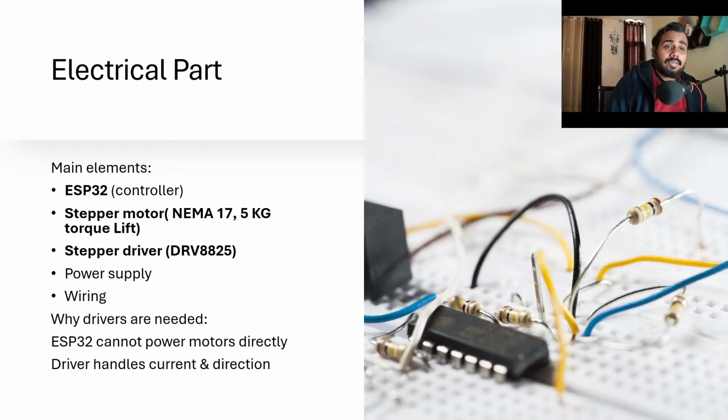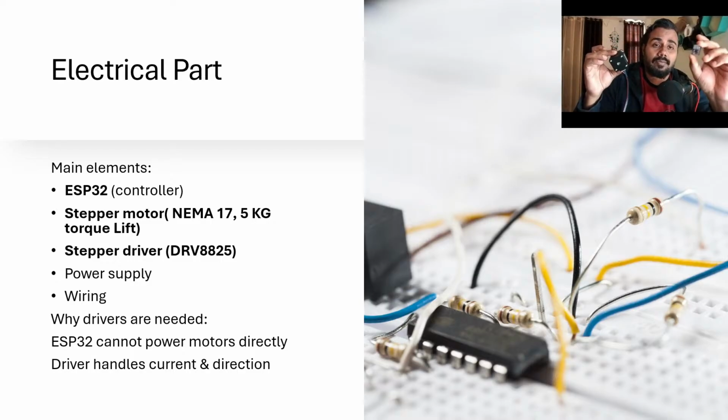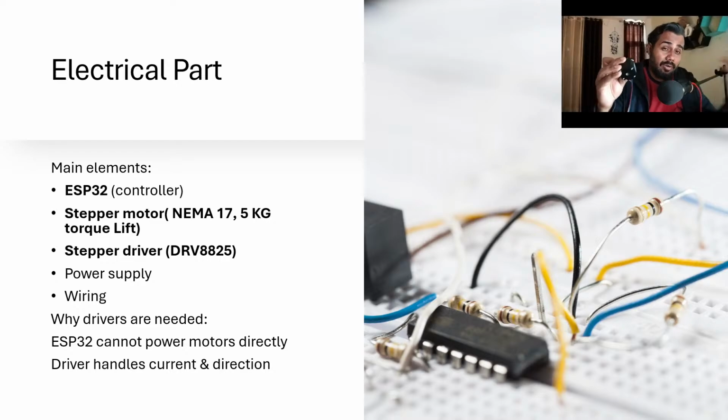Why are drivers needed? The drivers that I showed you, we cannot connect the motor directly to the ESP32. We need a driver to handle the current difference, because motors draw a lot of current, and our ESP32 operates on minimal current, and its voltage is 3.3 volts up to 5 volts, I believe.